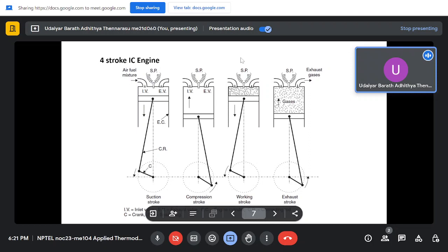This temperature is equal to or greater than the fuel's combustion temperature, so when the fuel is injected, it will start combustion. It will start reacting with the air, combust, and form exhaust gases, which are removed again. That is the difference between the compression ignition engine and the spark ignition engine.